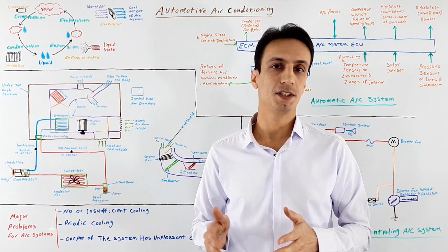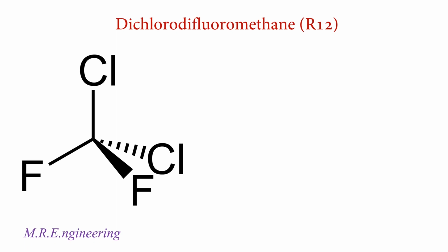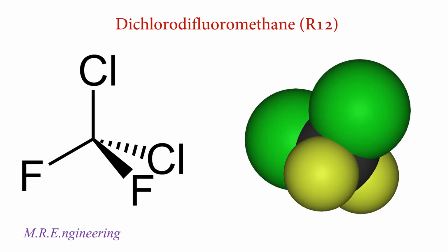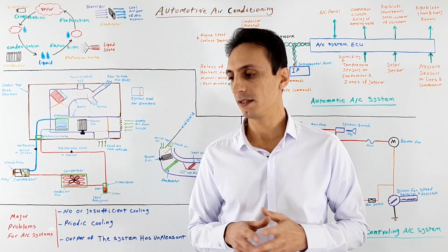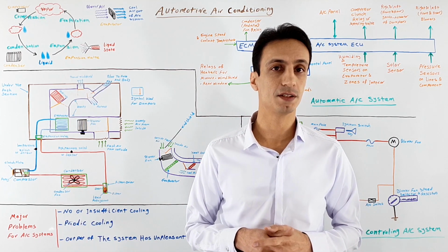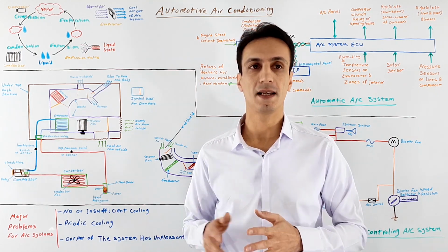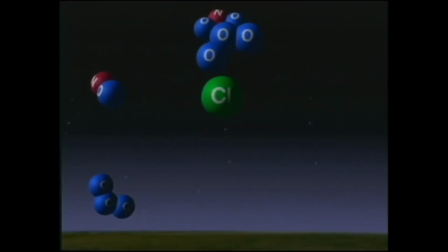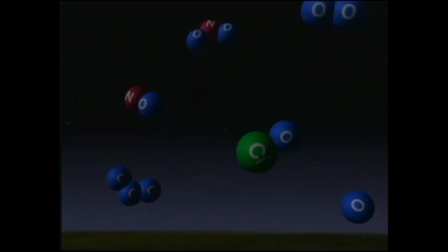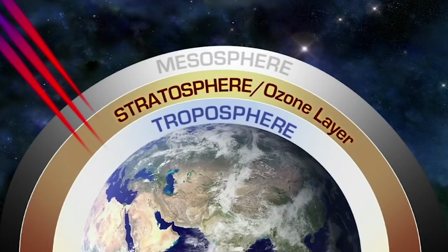One of the first refrigerants that was used in mobile AC systems was CFC-12 or R12, that is known as a Freon with boiling point of about minus 22 degrees Fahrenheit. But this R12 refrigerant had some major drawbacks. This gas is known to be an ozone depleting gas, and it means that chlorine content of this gas reacts with ozone gas in ozonosphere layer of the air under effect of UV rays and makes this layer weak over some areas of the earth.